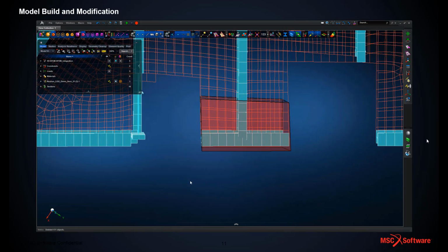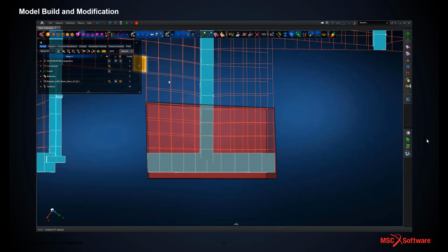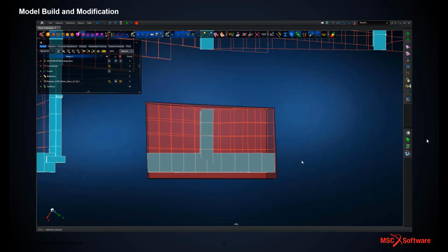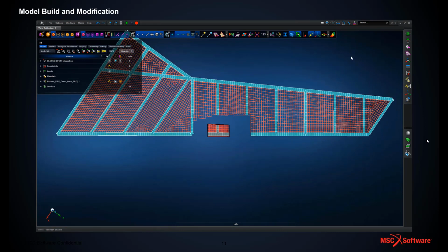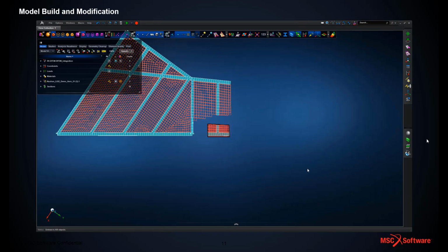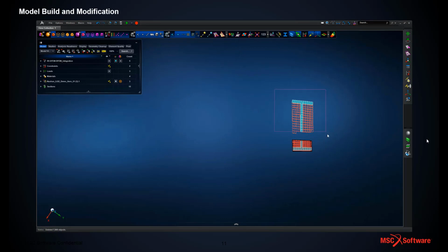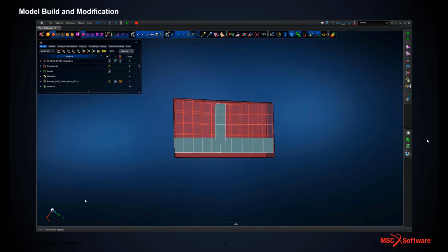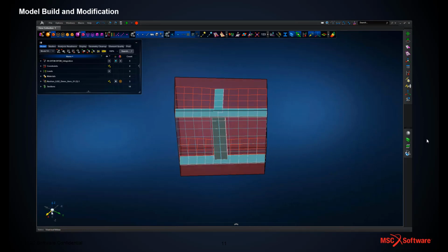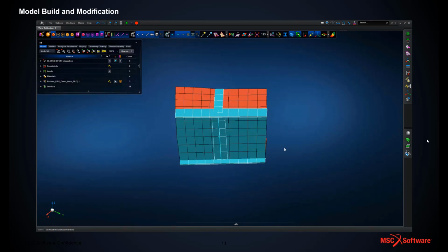Again, no back and forth to forms. We can do all of this from the cursor support, removing the full extent of the model but retaining the area that we wish to work with for our subsequent model build. So just tidying up the model, and again there is a Python API to support this if you wanted to automate this process. One good example would be to delete all the elements that don't sit within the bounding volume, but let's just look at some manual approaches here.